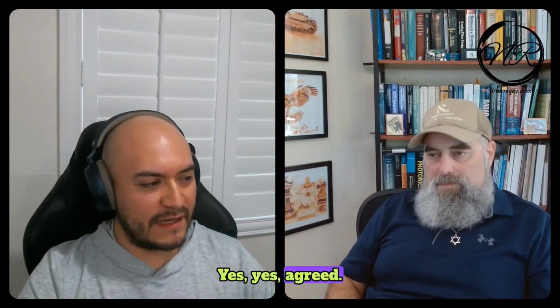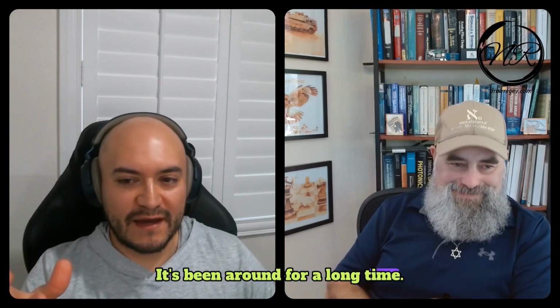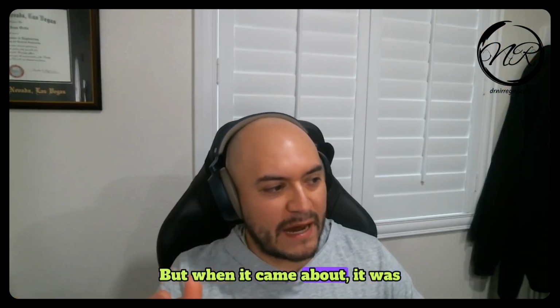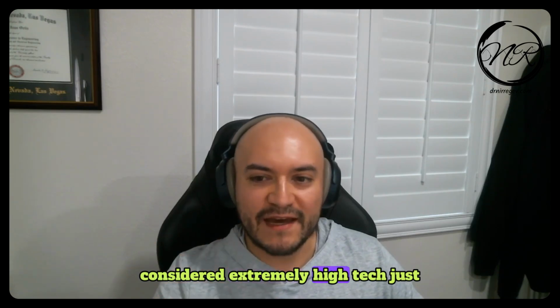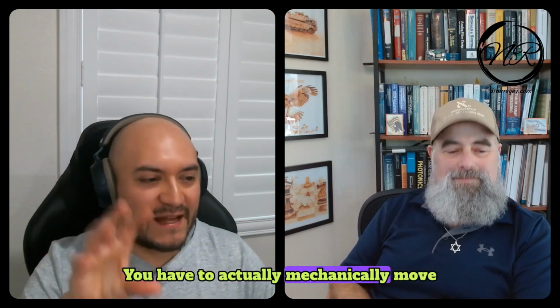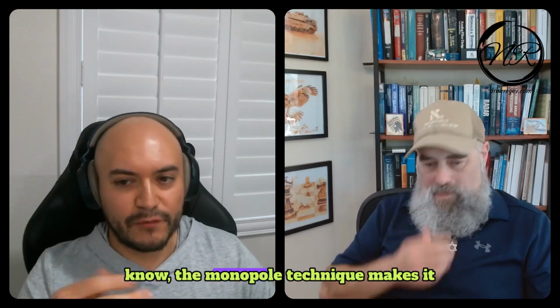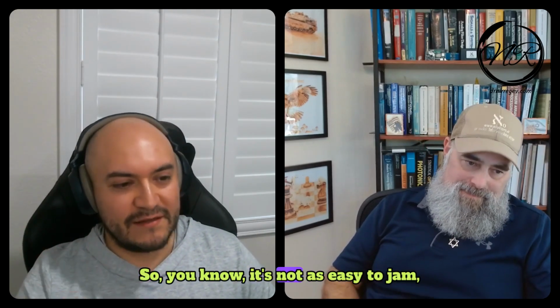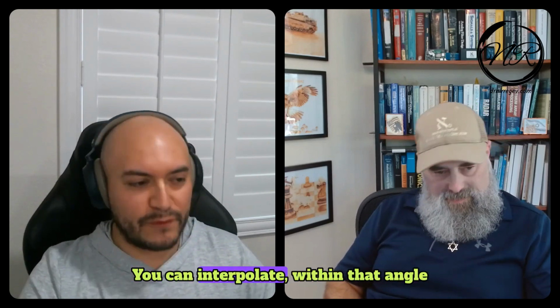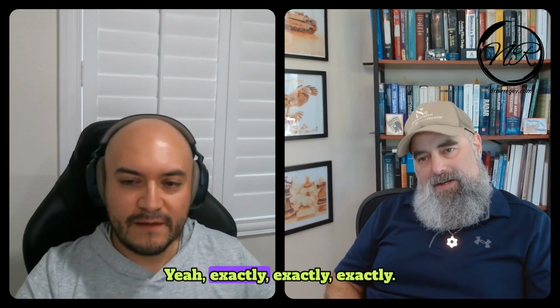Agreed. And just some history: monopulse is quite old, but when it came about it was considered extremely high tech, because we were used to conical scan. You had to mechanically move the beam around, and you were dependent on target amplitude, which is exactly what the monopulse technique makes you agnostic to. So it's not as easy to jam, and it's more stable. You can interpolate within that angle range. Usually the main beam is what you're concerned with.